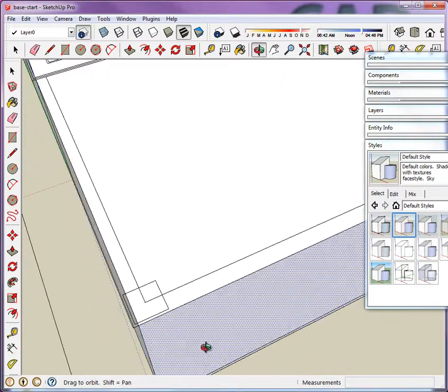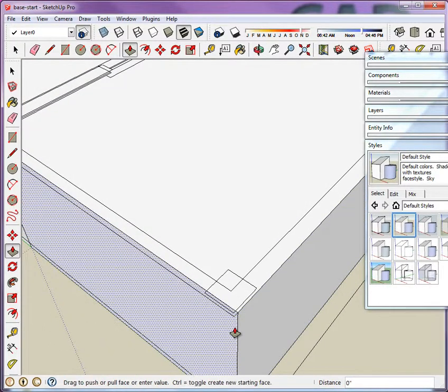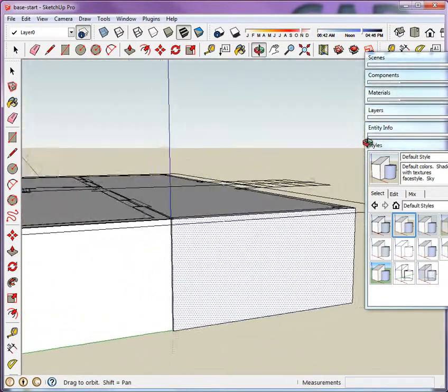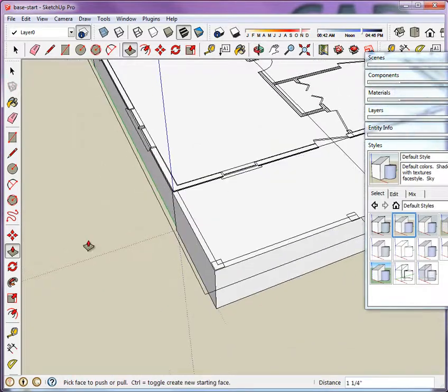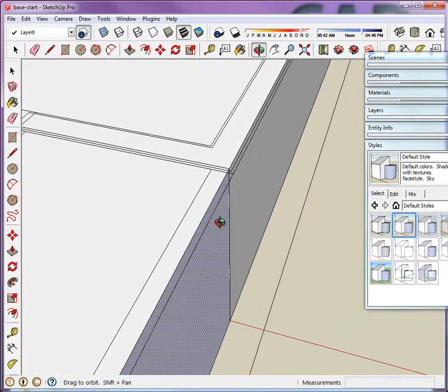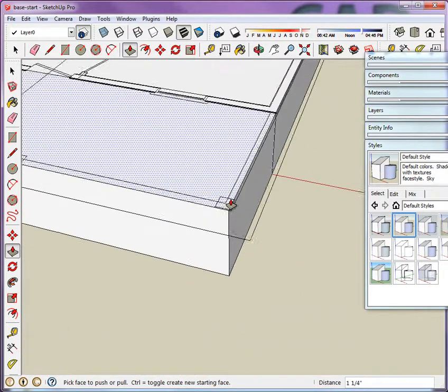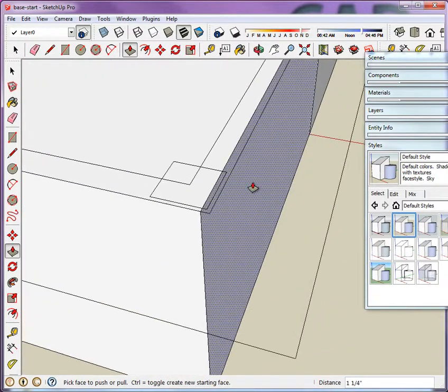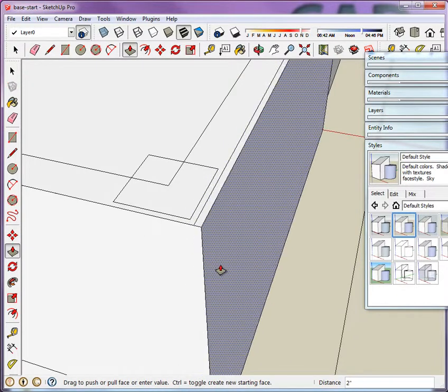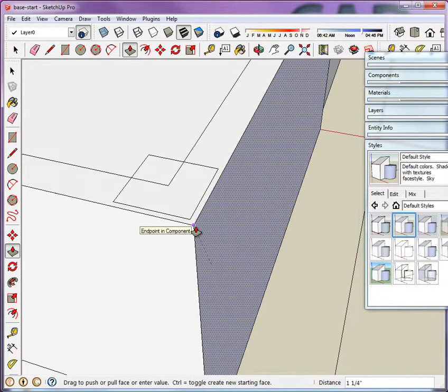Now you'll notice this side is a little bit short, but again, I can just push-pull that edge and have it align with the vertex or any point in the model that is the reference. Okay? As you can see there. Let's try that again on this side. All right, so if I look here, you can see it come all the way forward, but I have this little portion that I have to add. So if I click on the face with push-pull, just pull it and then align it with the edge in the DWG file there.